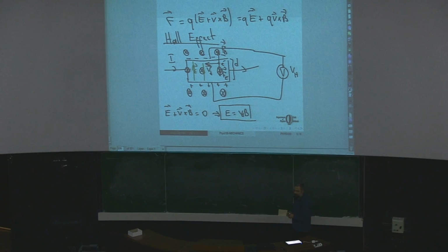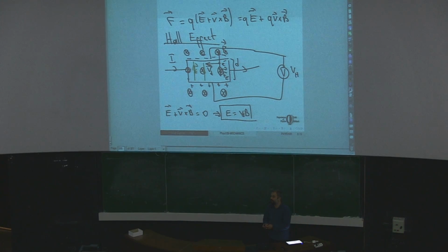Yeah, that's fine. You should be able to measure it yourself in the lab. You have the necessary equipment. Just pick up a voltmeter, just pick up one piece of aluminum foil, take some magnets. Magnets are cheap now. You can have a magnet which has a large magnetic field and see if you can measure this Hall potential. It is short. It doesn't take long.